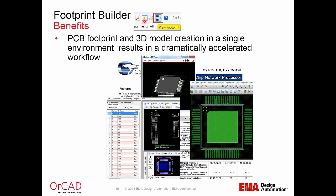So by clicking the footprint, one can choose the particular IPC calculator. We also call them templates, but an IPC calculator is termed that because it actually has mathematical equations behind that particular template, so by changing the package size, it will automatically adjust the pads for the PCB environment. So it'll calculate those, as well as create step models based on that data.